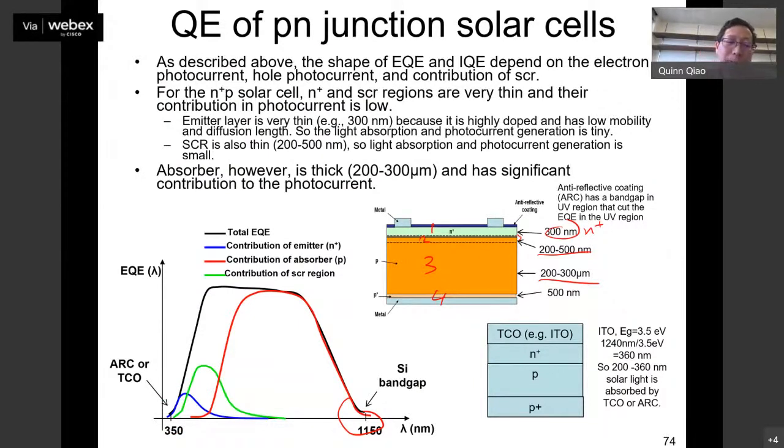If you see, in these regions, in the blue green, you will see the space charge regions have some problem. If you see the main body here, somewhere like maybe 700 or 800, 900 nanometers, then you see problems from your P layer. And then if you see near infrared regions you have some problems on QE, then that's from the back contact. Okay.